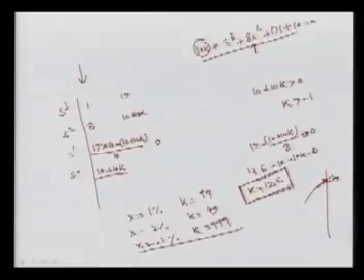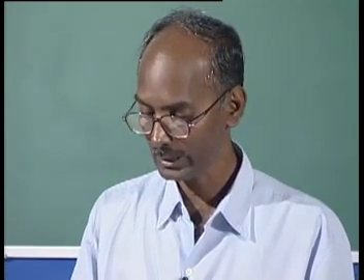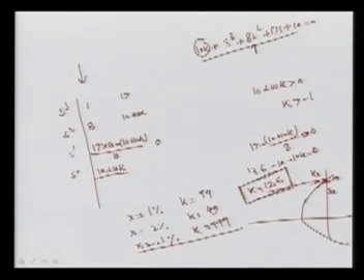Again, now we can also determine what will be the pole or root and where it will be. Means here I obtained the k value, that k we calculated. Now I want to know what will be the s value, what will be the root, what will be the magnitude where it is crossing. Means we had this characteristic, if you remember, and one root is crossing here, it was moving like this and going like this. So I want to know this value of s here, and that can be obtained by the auxiliary function.